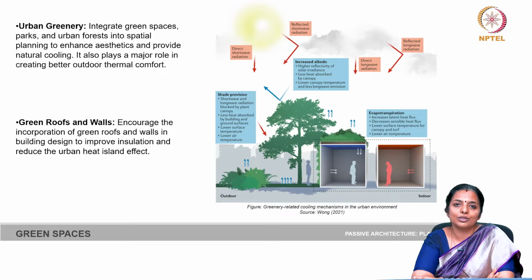Again, a new terminology you are learning now, because roofs can radiate a lot of heat, whereas having cool roofs will absorb, because there is vegetation on a cool roof. It will absorb the radiation and not radiate the heat back, and hence it reduces the impact of urban heat island effect. And it offers benefits such as thermal regulation, improved air quality, and sustainable stormwater management.